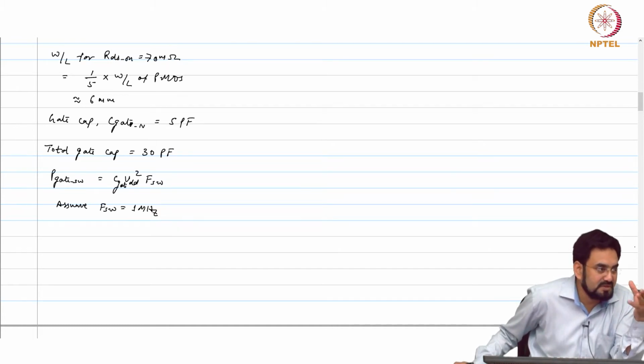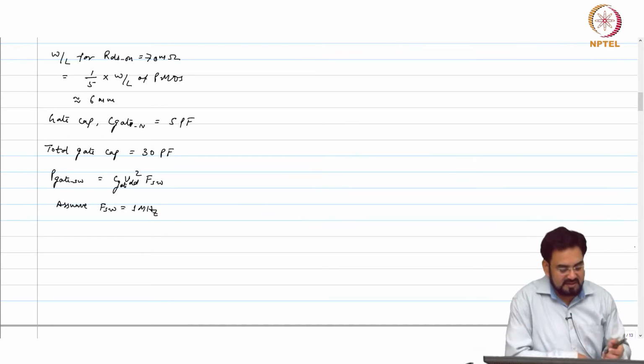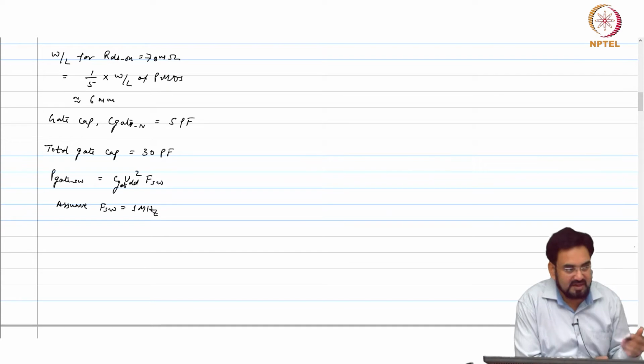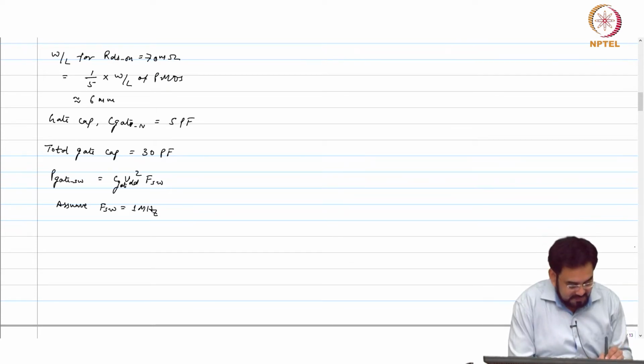Okay, so at 1.2 volt and 1 amp, 120 milliwatt was the total loss. So we want to see how much we have switching losses compared to 120 milliwatt, and then we'll decide whether we can have a higher frequency or 1 megahertz is the max limit.